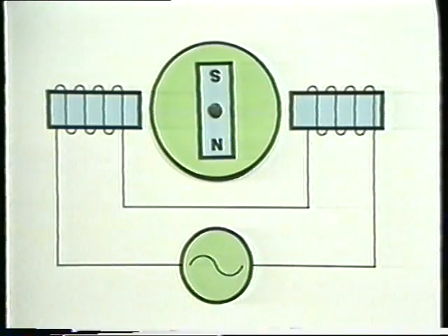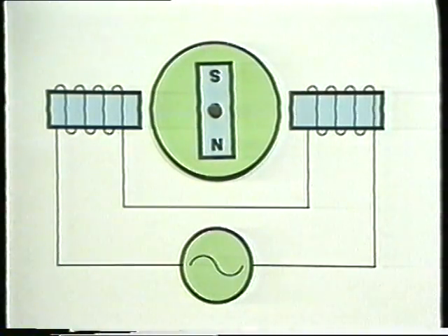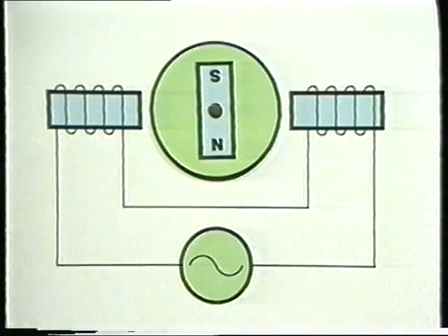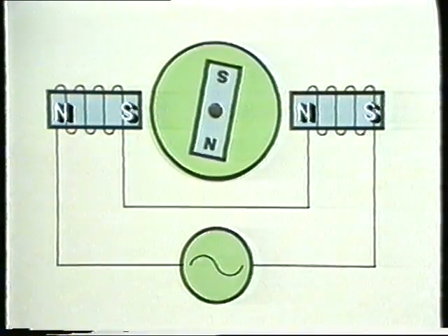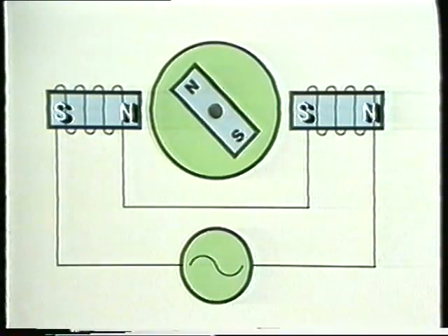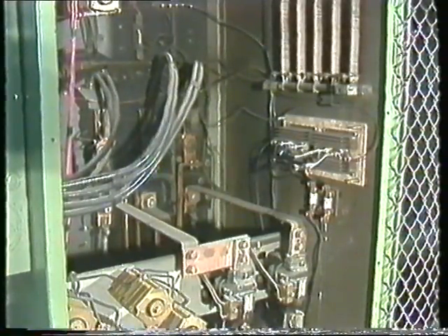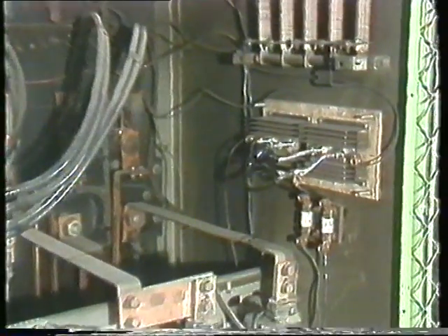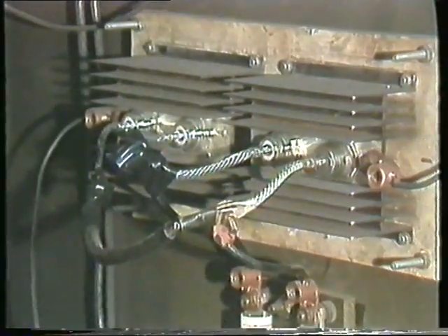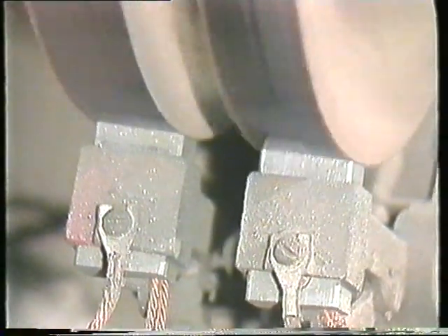In a synchronous motor, the rotor poles are not produced by induction. Instead, the rotor is either a permanent magnet or, more often, an electromagnet with its own source of direct current and its own poles. When the motor is running at synchronous speed, the rotor poles and the rotor are locked into step with the rotating stator poles. Direct current for the rotor coils often comes from a controller outside the motor. A rectifier in the controller takes AC line voltage and turns it into DC. Brushes riding on slip rings in the motor conduct the DC to the rotor.